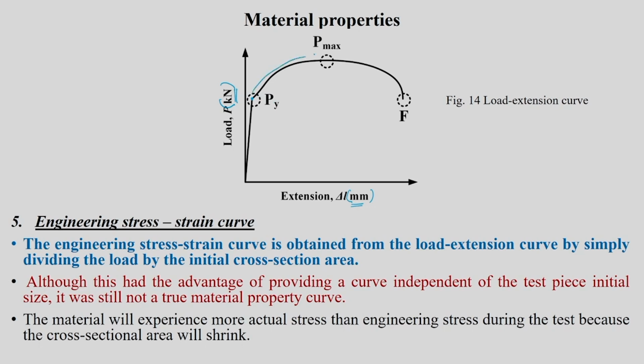This region you can call the plastically deforming region or plasticity region, and it reaches P max, that is the maximum load. You will see that after P max the material is going to deform with reduction in load, and it is going to come here this way, and you will have a fracture here. Okay, it is fully fractured. The sample will become two different regions like that.